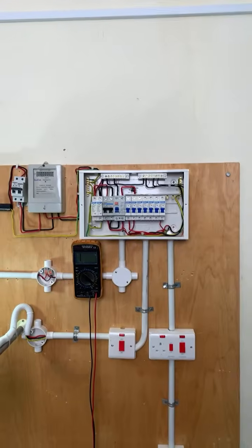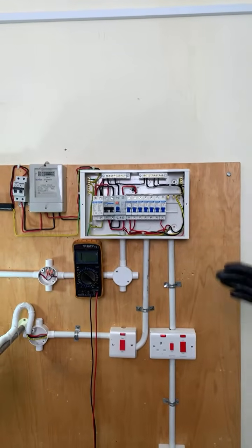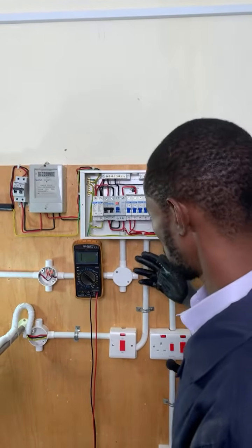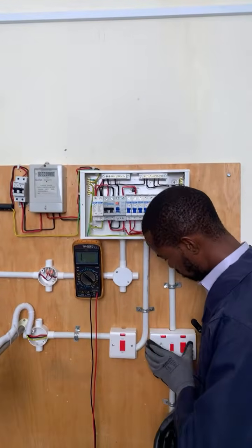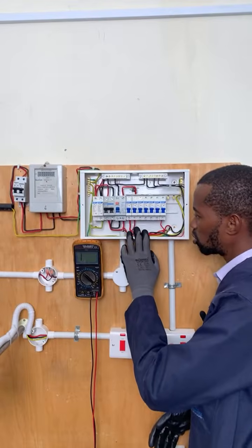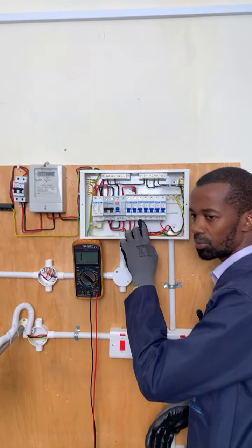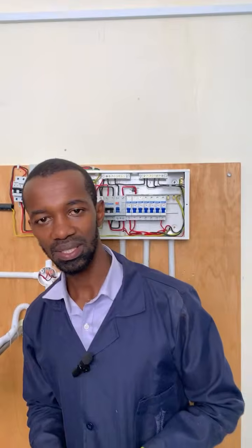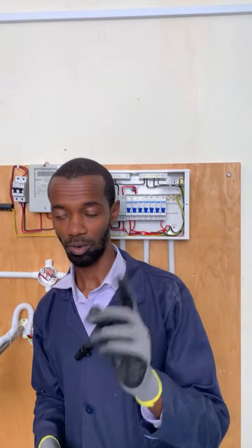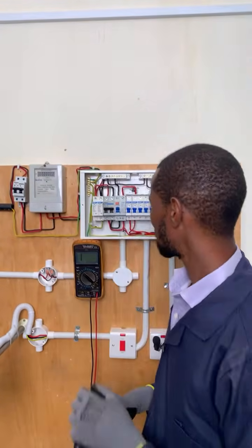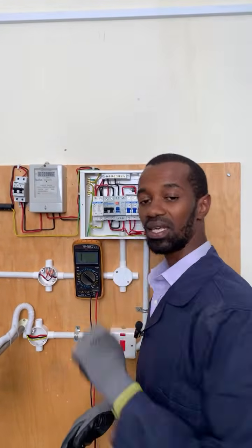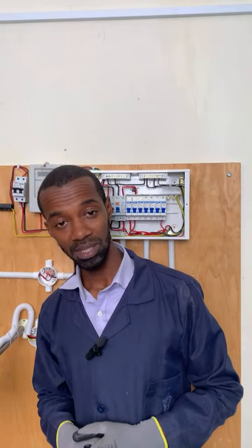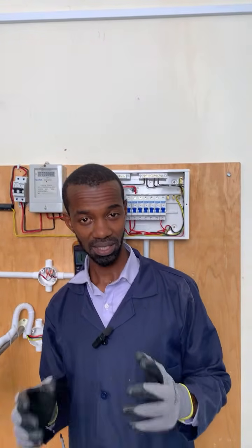So that being said and done, my top boss, the same applies to, let's say, the sockets, right? Assuming that we have this socket not working, you simply go to the MCBs. If in the MCBs there's one that has tripped, you know there's a problem. And there's also another chance that the MCB might not have tripped, but there is no voltage output at the MCB. Could that be a scenario as well?